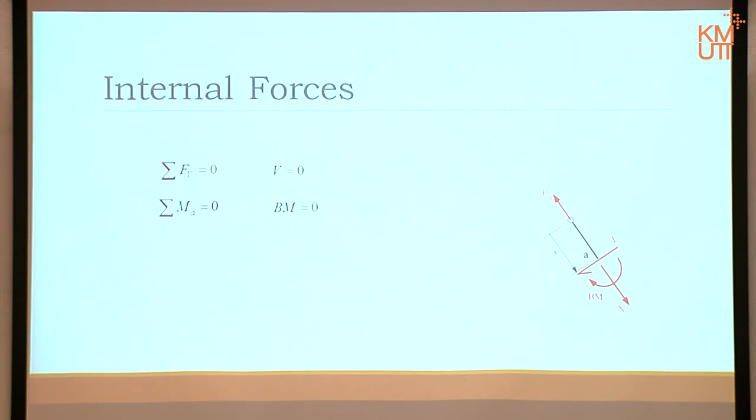There is no bending moment in a pin joint truss either. Left with one: sum of F in that direction gives F equal to N, N equal to F. In other words, the axial force N is not 0, or at least it doesn't have to be. It could be in some cases, but it doesn't have to be.